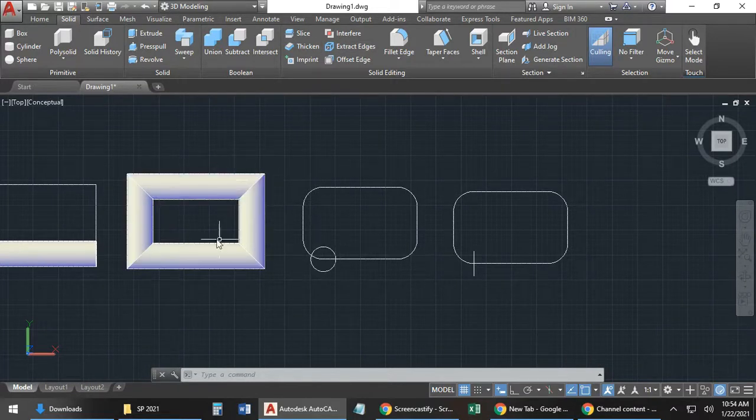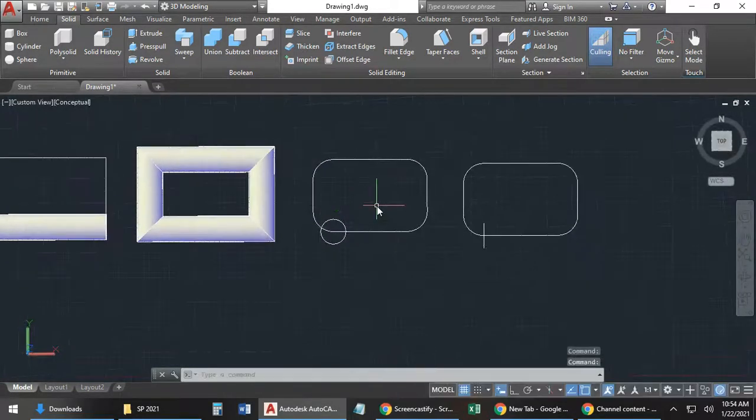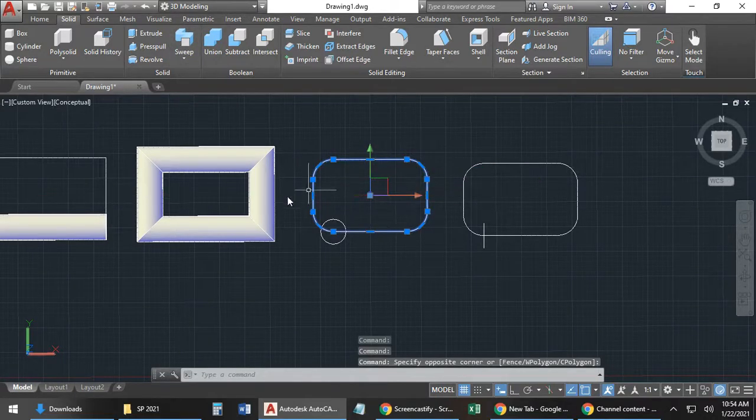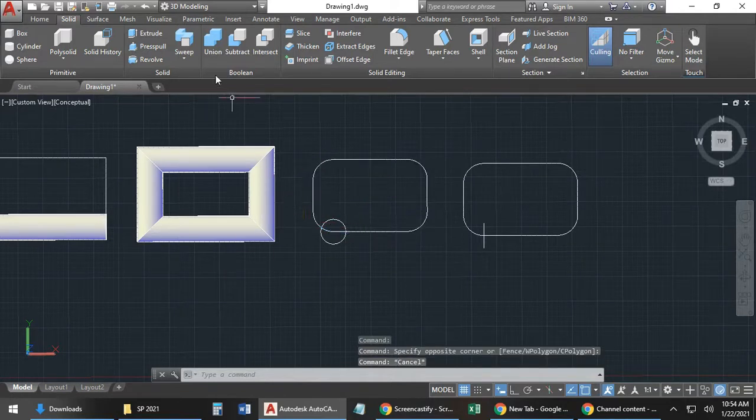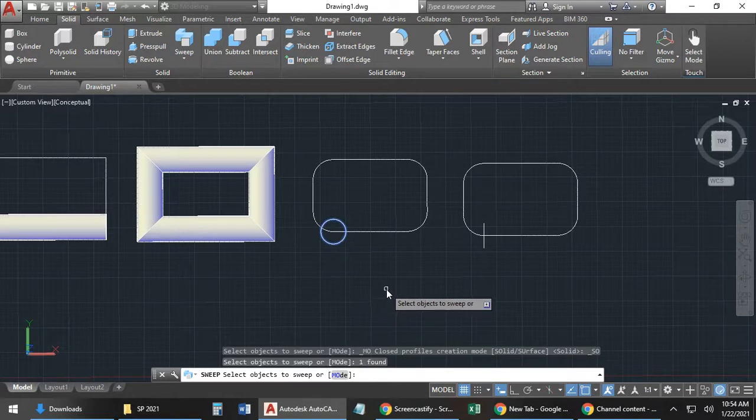If you want rounded corners, so notice on this rectangle here, it has square edge corners. And so it breaks that pipe or that rounded piece there about the 90-degree corner. If you wanted it to be rounded off, I have made a rectangle. I've filleted the edges, and I have the same circle. So here, I'm going to now use my sweep command, same circle, press enter.